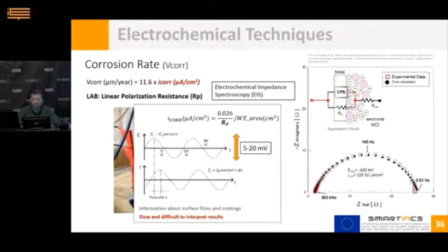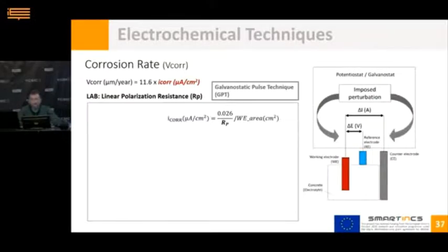However, in practice, interpreting the results may be difficult, and the use of an equivalent circuit, which can change according to the steel condition and should be modified depending on the study, makes the technique difficult to implement on-site. So this technique is usually for laboratory studies. This has led to simpler techniques